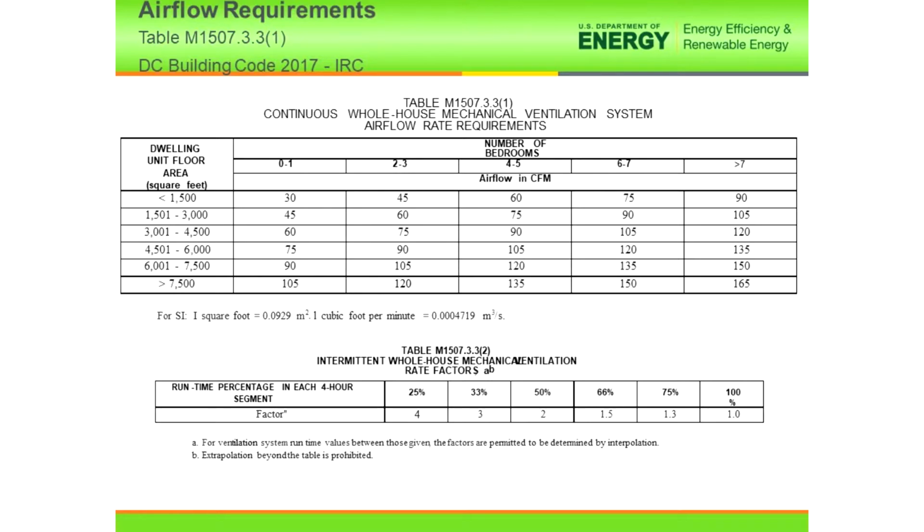Now, on top of that, when you are mechanically ventilating a dwelling, there are various ways you can do it per code. You can do exhaust only, you can do supply only, or you can do a combination of both. They have their pros and cons. With exhaust only, of course, you are negatively pressurizing the home, and you're forcing outside air to come in through whatever leaks still remain in the house. Likewise, if you do supply only, you help to push air out, but you still bring in outside air.